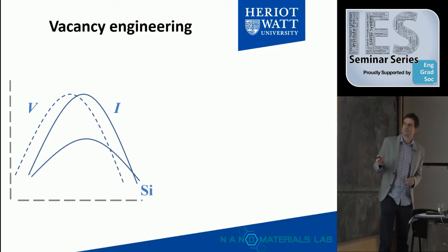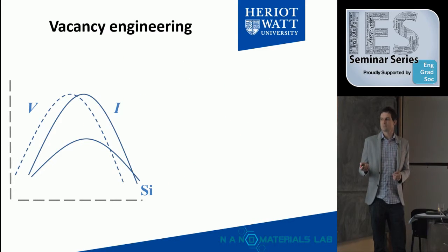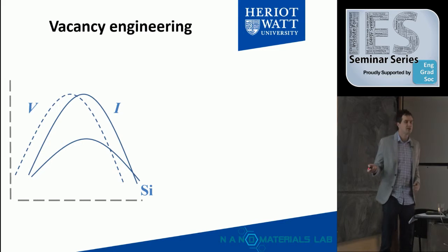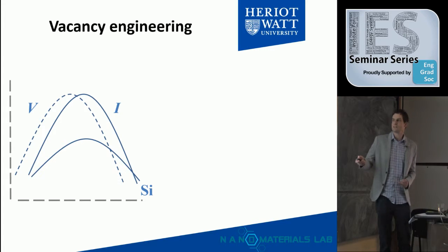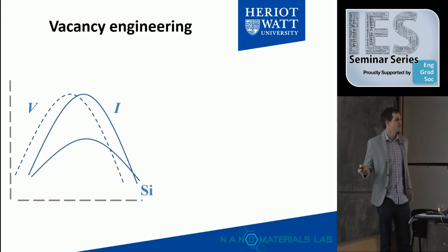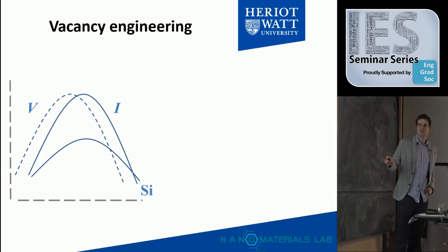And when we do this over a large substrate, we get something a bit like this. If this line is the surface and this is into the depth of the crystal, we get our silicon ions with this type of distribution. We get a lot of interstitials created, and just slightly shallower we get the vacancies where these interstitials have originated from.